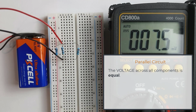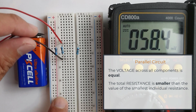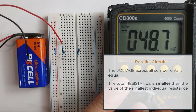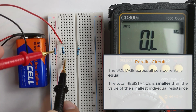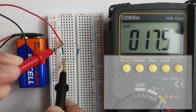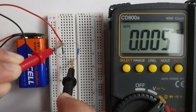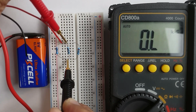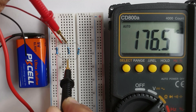The second principle is that the total resistance in a parallel circuit is smaller than the value of the smallest individual resistance. Recall that in a series circuit, individual resistances are added to get the total resistance. However, in a parallel circuit, we compute it differently. Notice that if I measure the resistance across these three resistors, I am only reading roughly 177 ohms, even though I have 10 kilo ohms, 1 kilo ohm, and 220 ohms resistors in this circuit.